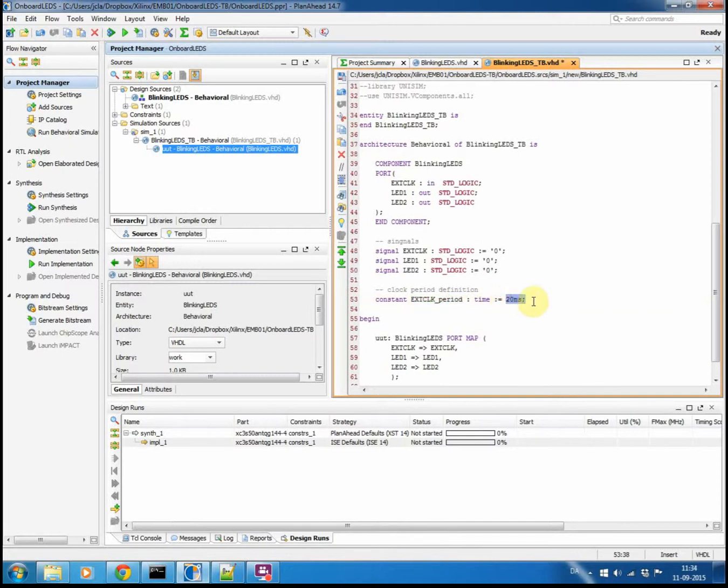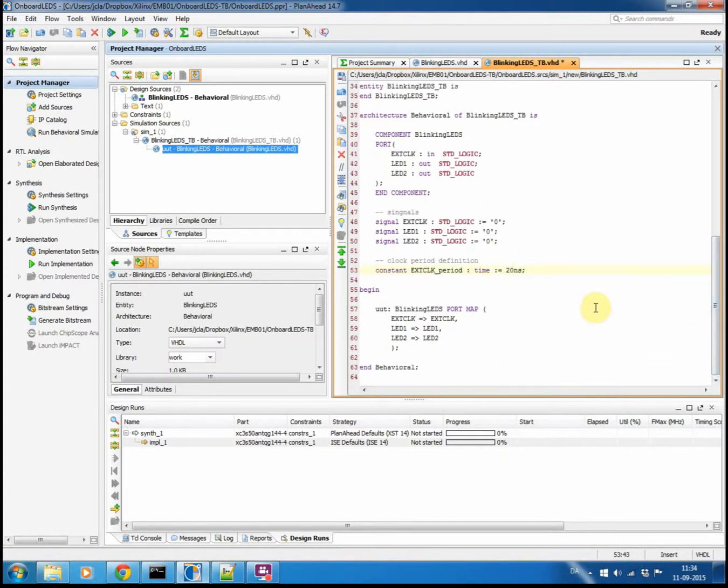You might now ask, why are you able to write 20 nanoseconds? In VHDL, you cannot define time. Time is just something that happens given the laws of physics inside the FPGA. And that's where the simulation can play tricks with you, because in simulations you can set up timing. You can say that you want this signal to be high for a certain amount of time, or you want to insert a delay here. That's something you can do in simulation of VHDL, but you cannot do it in implementation of VHDL.